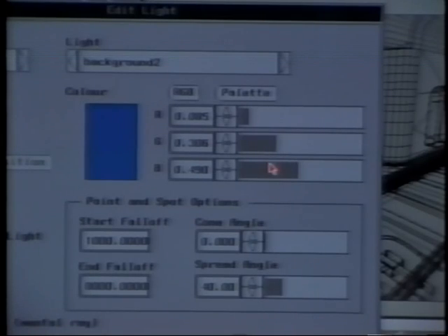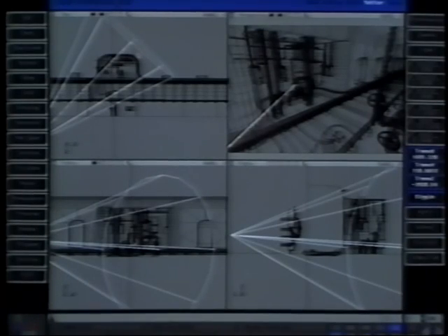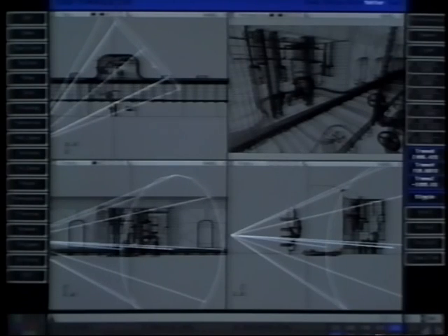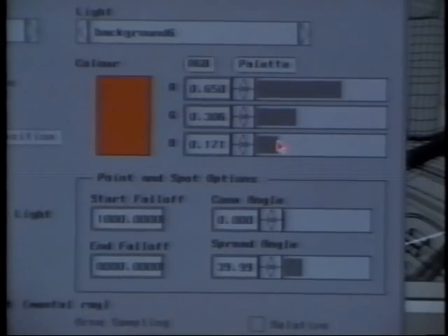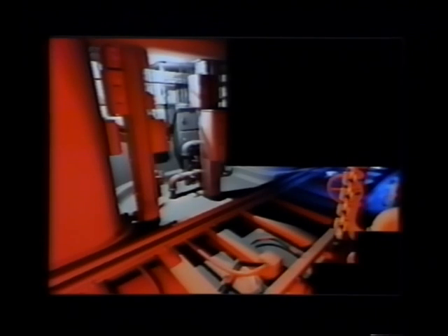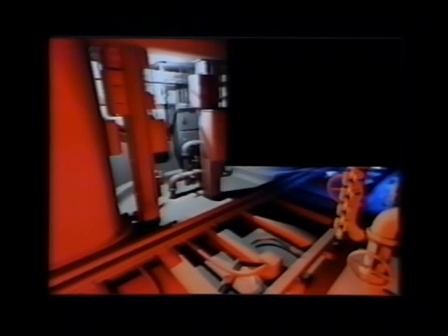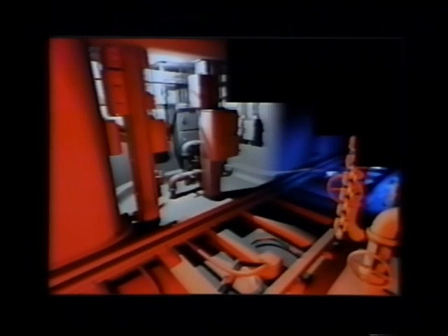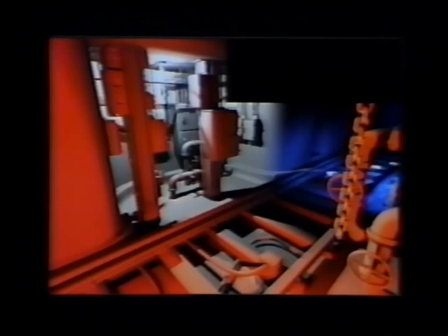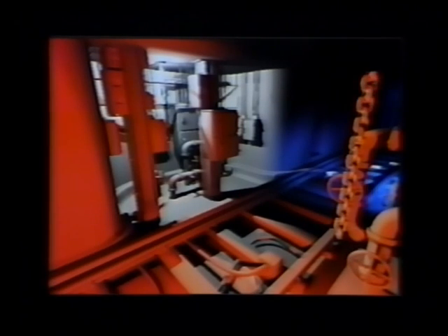Now we can also add a fill light, and we want this one to look as though it's coming from a red signal light in the tunnel. Warmer colors, especially if we choose a hot red, pop out into the foreground when seen against cooler background tones. Remember that the purity of color in this preview will be tempered and made much more subtle when we load in the materials and textures for the scene.